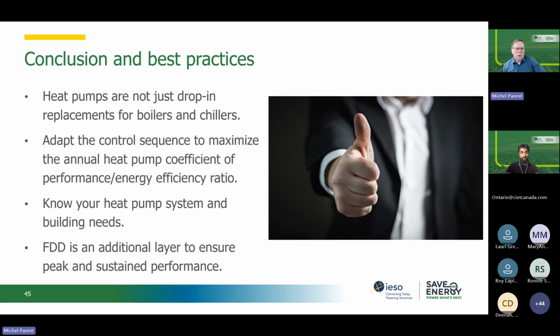Curtis, did your previous rooftop have cooling in there? Yes. It's surprising. Usually there is a slight weight difference between a heat pump rooftop unit and a gas rooftop unit. Yes, you do have the supplemental gas, I would assume that's still there, but the heat pump is really just an air conditioner with a four-way valve, so the weight difference is typically not enough to cause that. But I'm surprised that in your case it did.